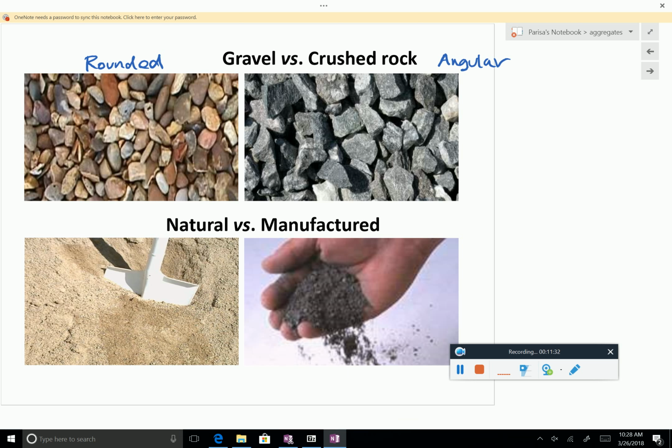And the other difference is just what your friend said. It's the color. One is colorful, the other is all the same color. So let's make it more technical. Gravel can have a mix of different rocks in it, because depending on the history, you can have different things in the river. But for crushed stone, you are getting the bedrock, you are crushing it yourself.